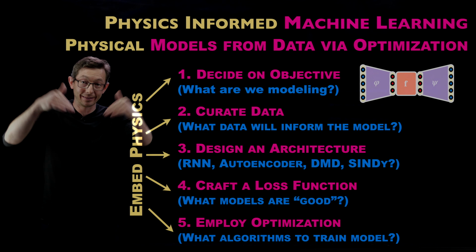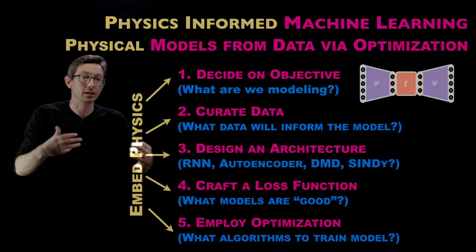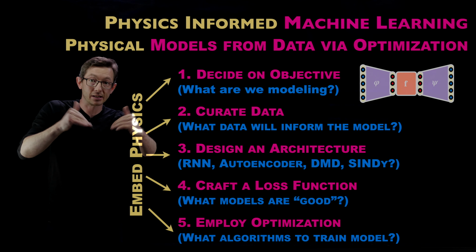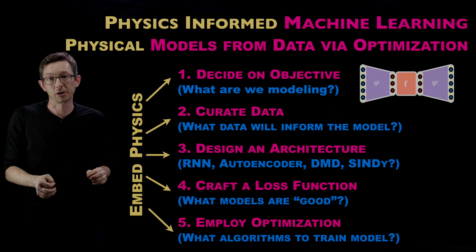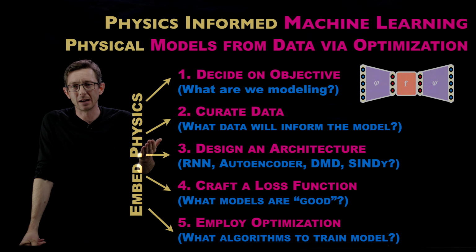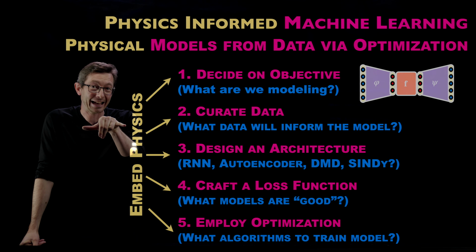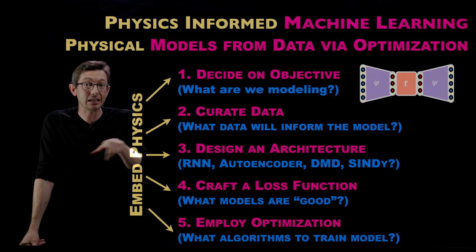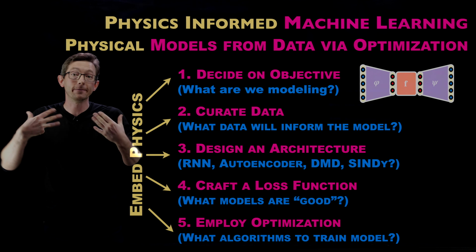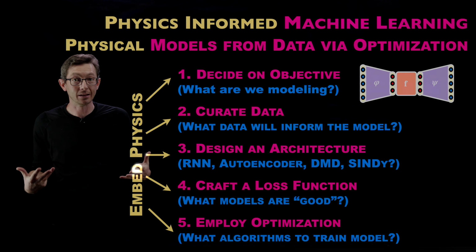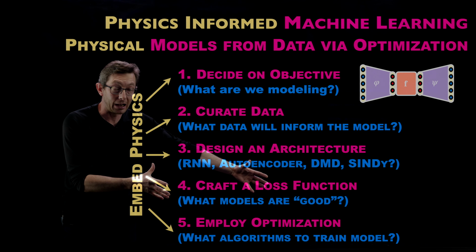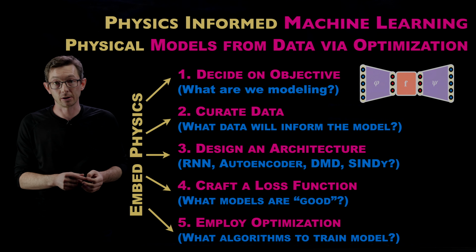And so that forces my optimization to try to minimize the divergence of my flow field as a term in the loss function. And you don't have to just do divergence. Anytime you know your partial differential equation, you can essentially add a loss term that says that PDE should be satisfied by the solution. That's the basis of the physics-informed neural network, or PINN architecture. Very, very popular, very, very useful architecture.